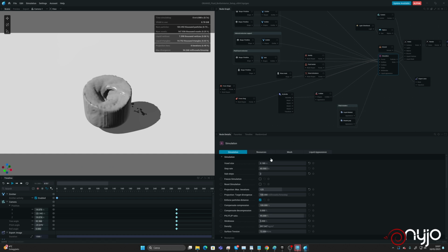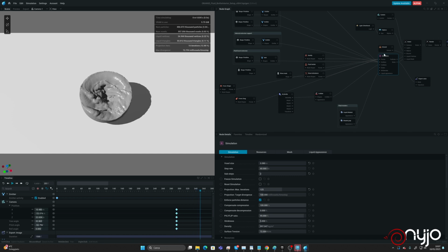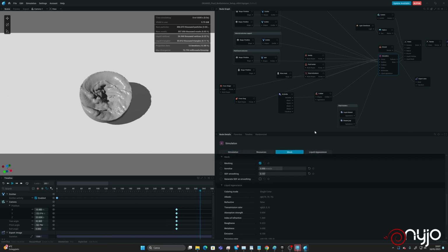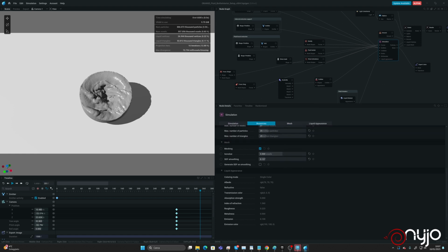So I like to go for a lower resolution. Let's try with 008, so a little bit lower than the initial setup. We should have enough memory. The resolution is not bad, but I like to double check about the meshing, so if we can have something that is better. We are going obviously to take care about the meshing to have something nicer in the 3D software.